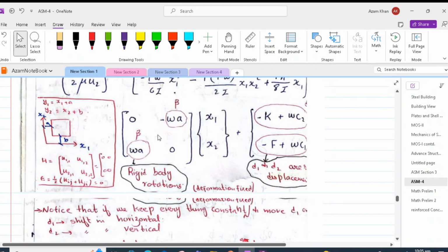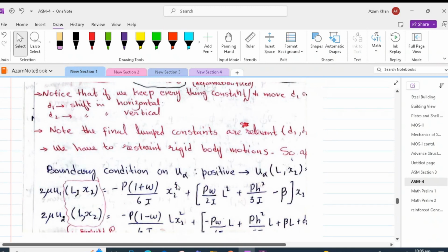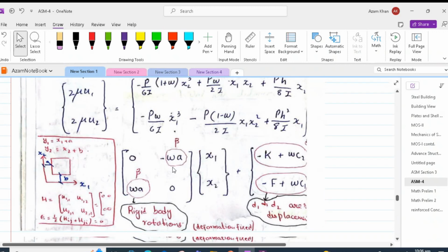This is clearly a rigid body rotation, as we discussed, and we will discuss in a minute how this is a rigid body rotation. But this one is clearly a rigid body displacement. So if we have a body at a distance AB and we just move it, that will give us a simple displacement. And if we put it in our strain equation, we will always get zero from this sort of displacement. Similarly, this rotation will also give us zero strain because it is purely a rotation.